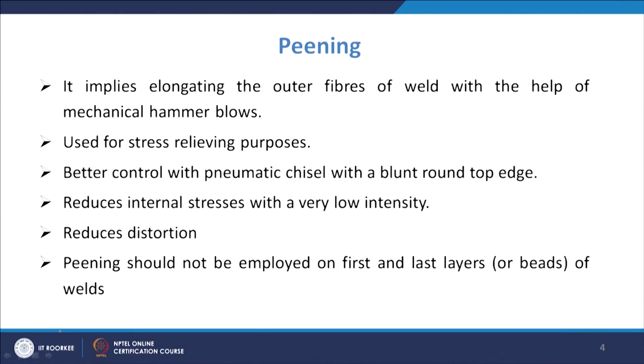You can do it by hand also, but if you use a pneumatic chisel with a blunt round top edge, you can have better control of the peening process. The peening process reduces internal stresses of very low intensity, and it will also reduce the distortion in the material.